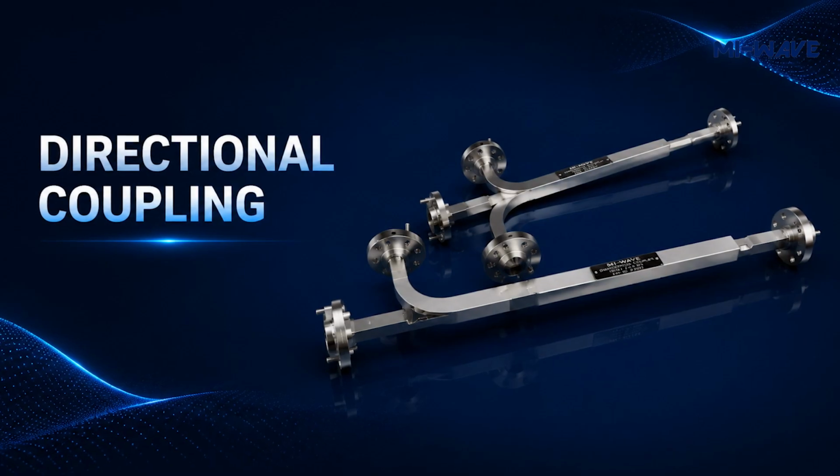An attenuator does the opposite of an amplifier. Instead of making a signal stronger, it reduces signal power by a controlled amount. Attenuators are commonly used to protect equipment, adjust signal levels, and support calibration and testing. A directional coupler allows a small portion of a signal to be sampled while most of the signal continues along the main path. This is useful when engineers want to monitor signal power without interrupting system operation.